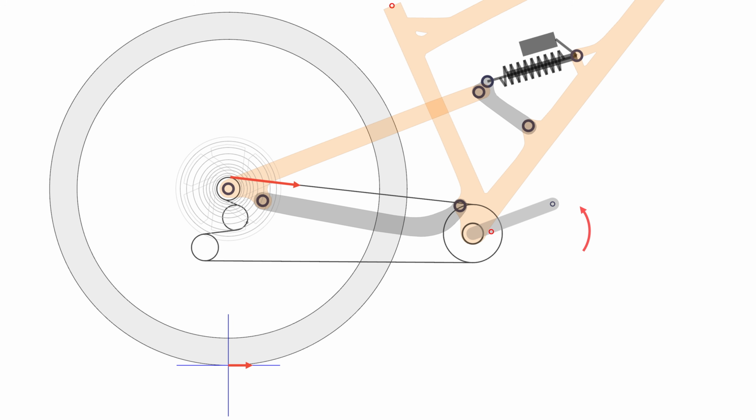When this happens, the rider experiences pedal kickback, and the anti-squat forces we discussed earlier come into play. Anti-squat only interferes with the suspension movement when the cassette is engaged. That is also when conventional pedal kickback occurs. You'll most likely encounter pedal kickback under braking or when riding slow technical terrain. In those moments, it can have a big influence on how freely the suspension is able to move.